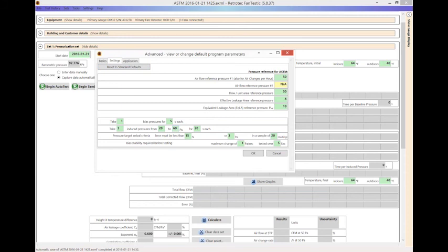Again, these parameters are now part of my ASTM test once I close it and save it. So I can open this up next week and hit find gauges, go test, and these are the parameters that it actually has stored for this version. It's very crucial that you remember that. So if you alter anything, it's important that you reset the standard so that you can make sure you're testing for that standard itself. Okay, I'm going to close this out.